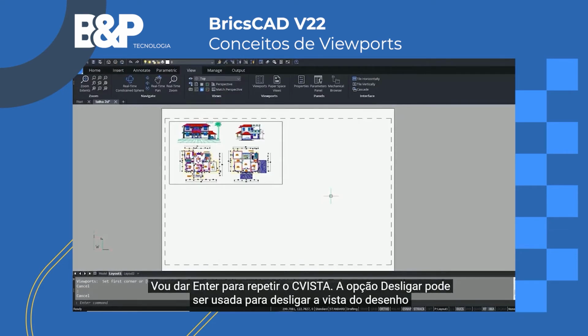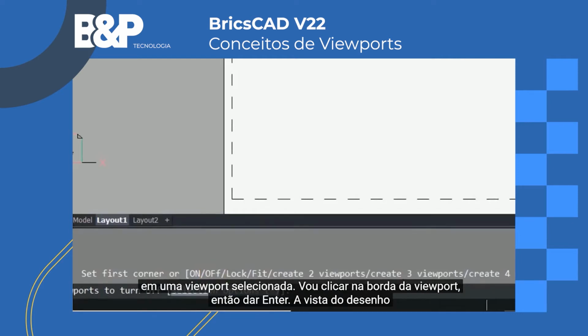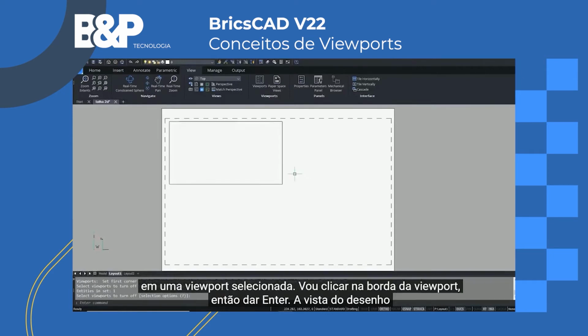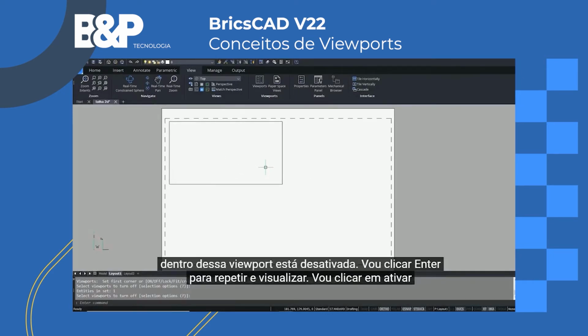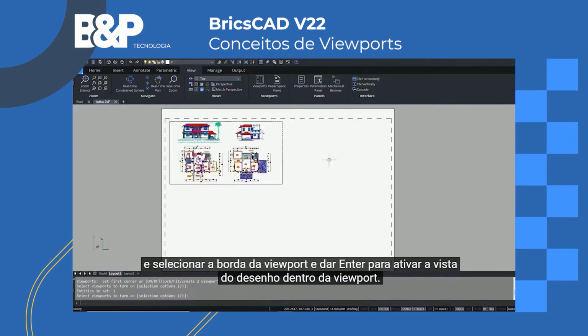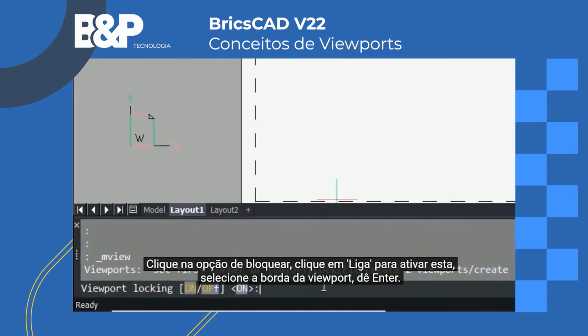Let's see rest of the options in the mview command. I'll give enter to repeat mview. The off option can be used to turn off the drawing view in a selected viewport. I'll click on the viewport border, then give enter. The drawing view inside this viewport is turned off. I give enter to repeat mview. I'll click on turn on and select the viewport border and give enter to turn on the drawing view inside the viewport.